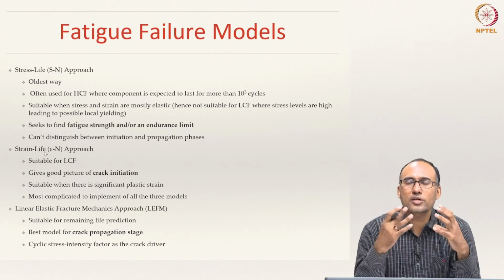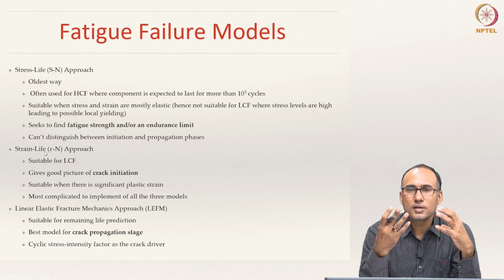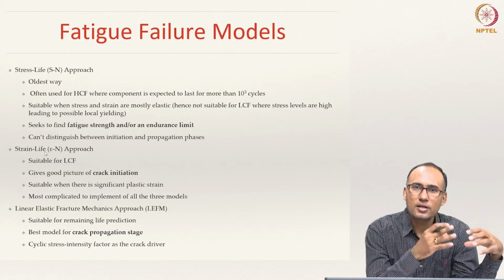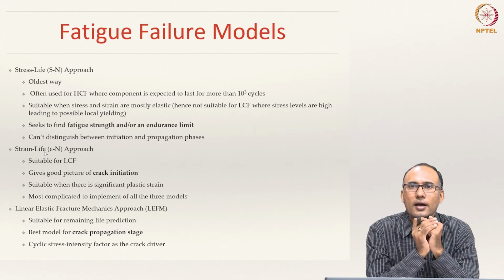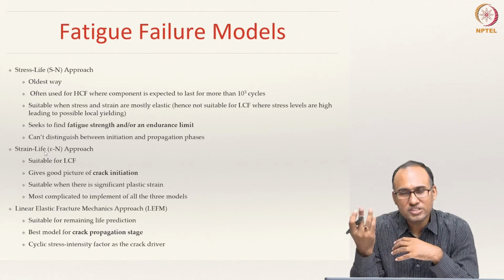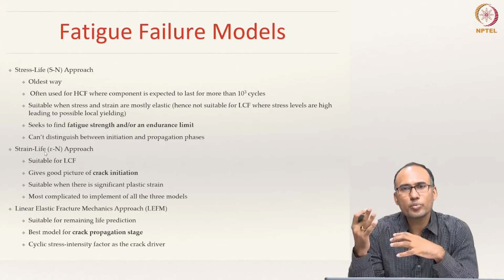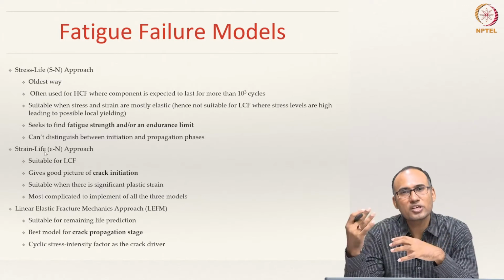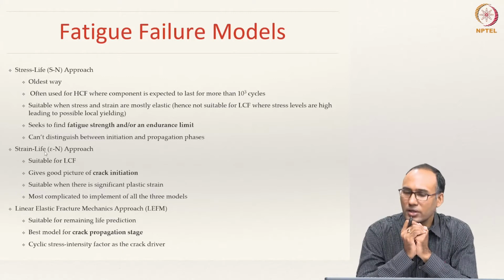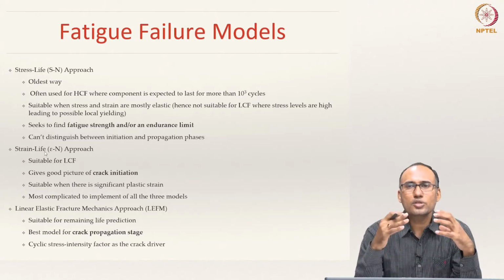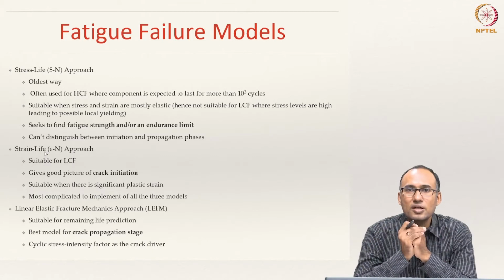would use in order to design a component which is expected to give a life of less than 1000 cycles is low cycle fatigue, and a component that is going to give a life beyond 1000 cycles is considered to be subjected to high cycle fatigue. Okay, fine. So now, in order to understand or design these components, what are the models that we need to use, right?